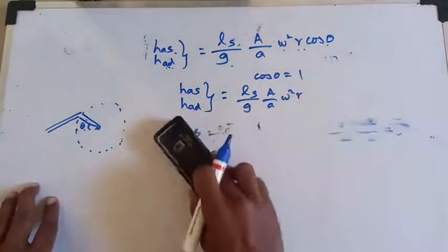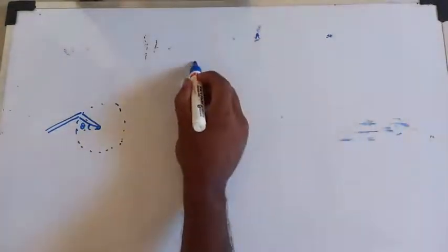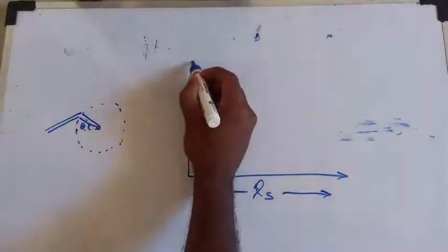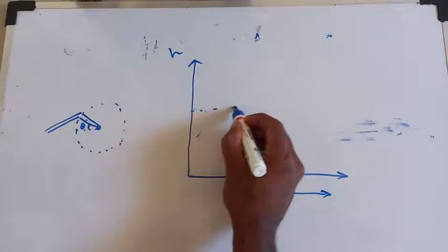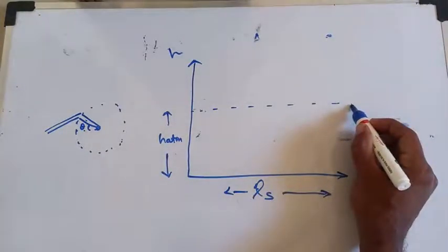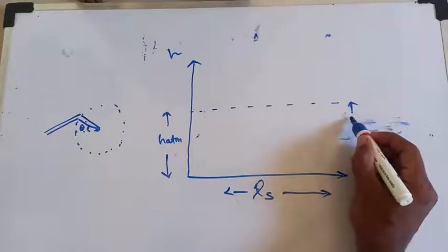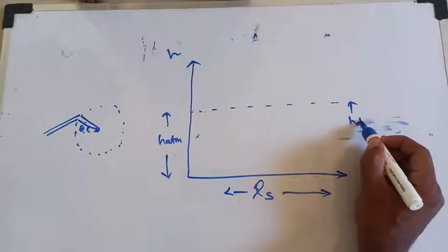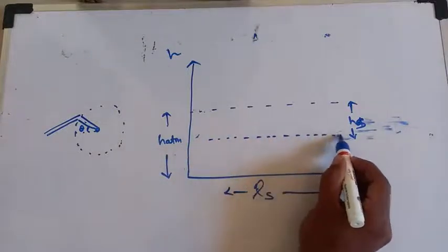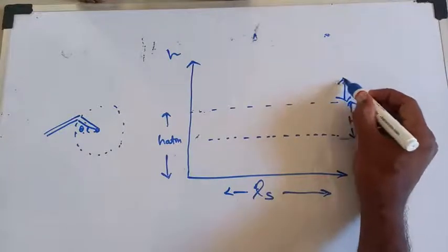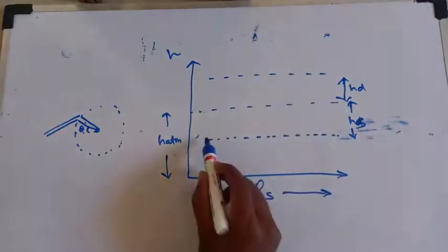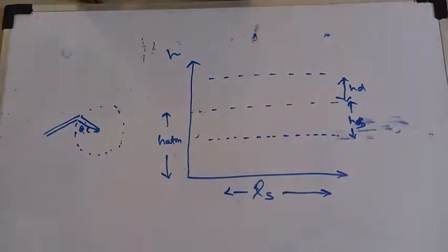Now let's see the indicator diagram. Without acceleration, we already know this is stroke length. Based on this stroke length, these heads will change. At center, we know H atmosphere. In general, without acceleration, this is suction head at the suction pipe, so its value will be lesser, and it remains constant. Like that, this is gauge pressure, this is vacuum pressure, this is gauge pressure at delivery, its value will be higher. So this is delivery line pressure variation, and this is suction line pressure variation.